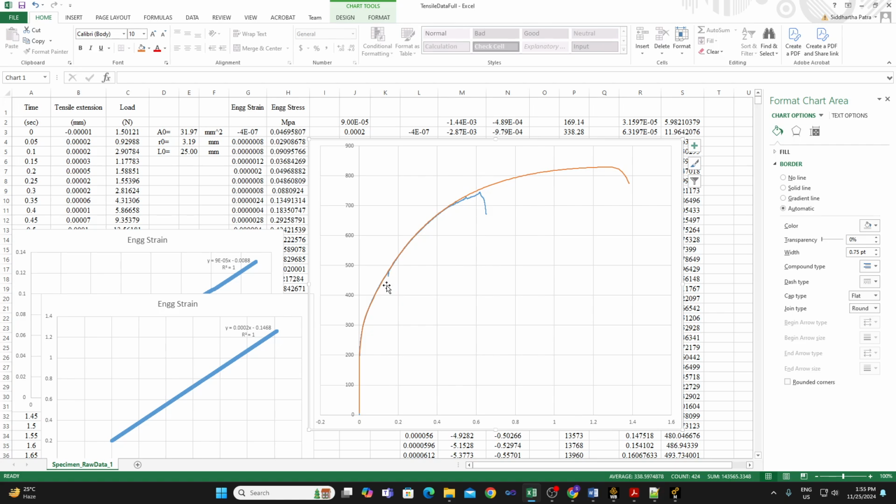Okay, so slight unloading is there over here, and also the stress over here is the total stress inclusive of the yield stress, and the strain over here is the total strain, and both are engineering variants, not the true stress and strain. So the stress strain diagram that we have fit by taking the data within the limits of the extensometer matches very well, much further beyond the extensometer limit. So it is valid to more than 40% of the strain. We had taken the data up to 15%, and it is valid for more than 40%. Let's say close to 50%, it is valid. But after that, the deviation happened, and of course, the ultimate stress values are different.